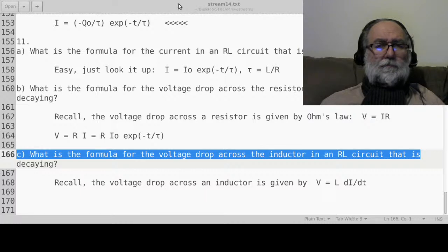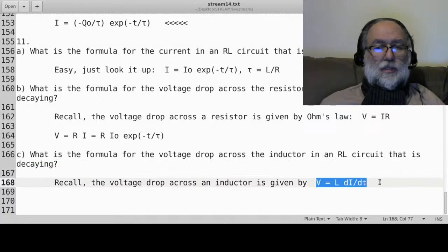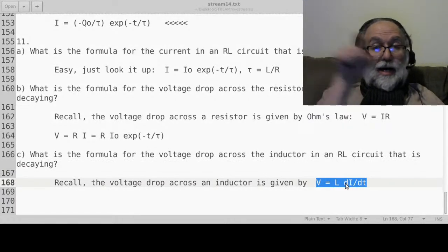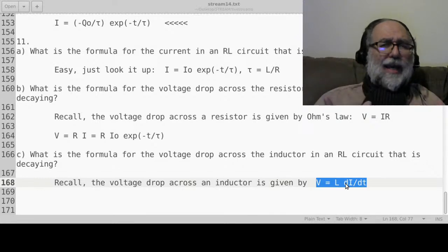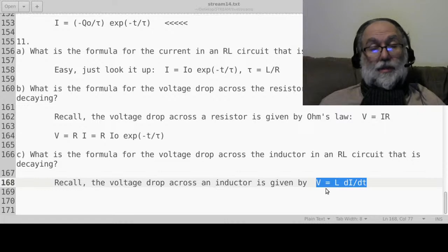Okay, and now you go, how do I get the voltage for an inductor? And it's equal to this. In fact, we had that formula above. Above, I had delta I divided by delta t. Technically, that's just average, just like velocities. You remember, at the very beginning of last semester, we had average velocities and instantaneous velocities. So here, if we do di by dt, then you're really going to get your instantaneous voltage across the inductor.